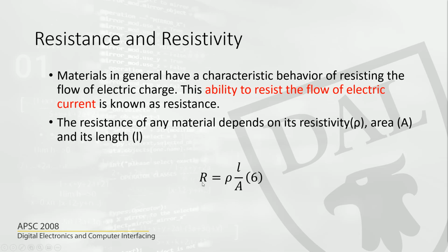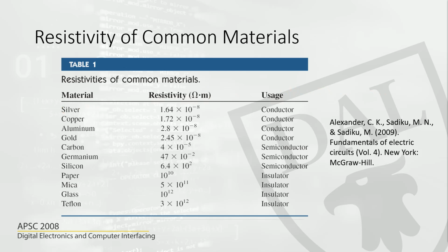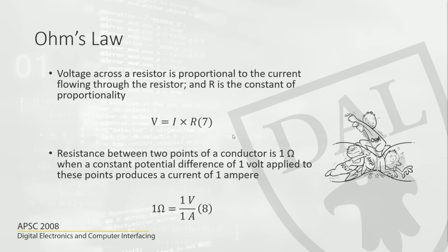So you take the product of rho, the resistivity, and length, and divide that by the resistance to get the area. Once you get the cross-sectional area, which is pi r squared, divide the area by pi and take the square root of that, and that should give you the radius. That is question 9.